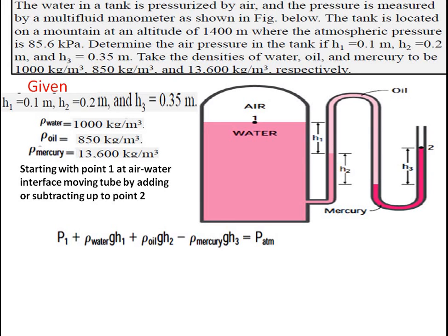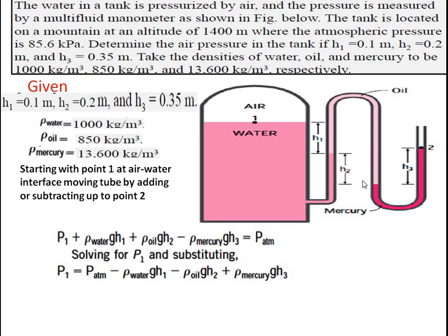P1 is the applied pressure here and atmospheric pressure is here. Then how to compare them? The mercury level stops here, so it is counterbalanced by atmospheric pressure. So atmospheric pressure is equal to the total of pressures here: P1 plus rho 1 g h1 plus rho 2 g h2 plus rho 3 g h3. By that we get P atmosphere.